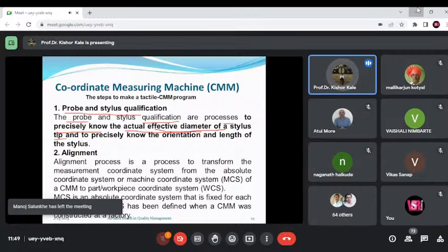Now if it is not aligned, we will find this is the distance between these two, and this is the distance between these. So we have to align such that distances between the corresponding points are minimum. This is nothing but the least mean square distance over the entire CAD model and point cloud.